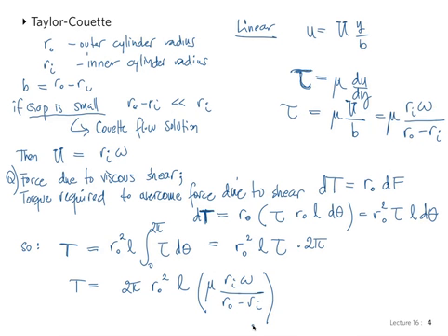L is the distance. Really we're looking at a cross section, but these are very long cylinders, and perpendicular to our original sketch is that L. So it's the full area of the cylinder where the whole force is applied. This situation represents an axis of some rotating machinery lubricated by a very thin layer of fluid, and that's the torque required to maintain a constant angular velocity omega.